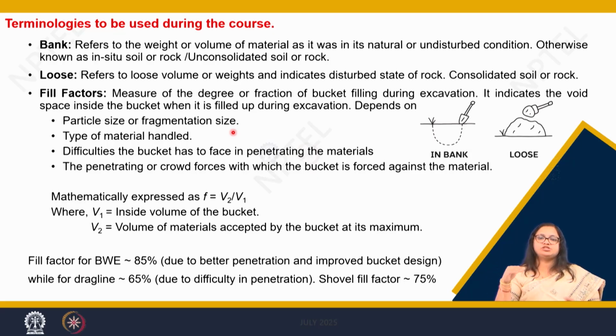The jar has a certain inner volume, which we call its struck capacity, and the amount of material that gets filled inside the jar has a certain volume. That volume divided by the total volume of the jar gives us the fill factor. It may be a certain percentage, and it completely depends on the particle size.